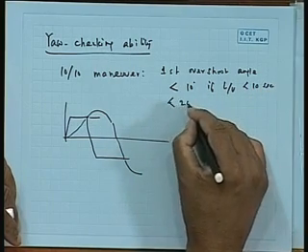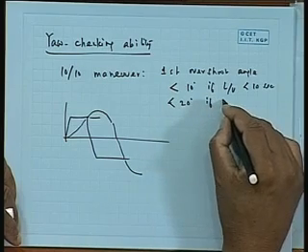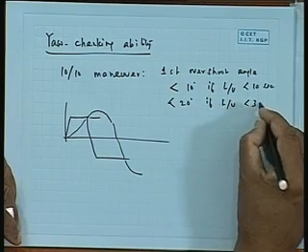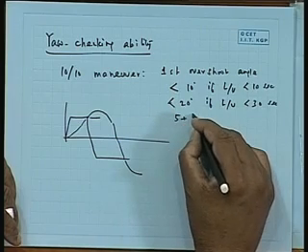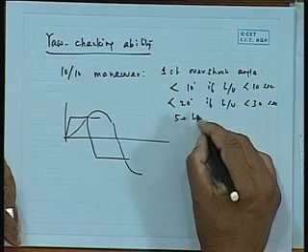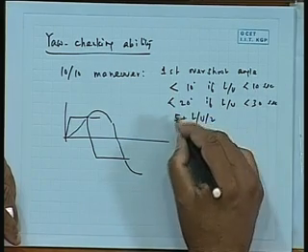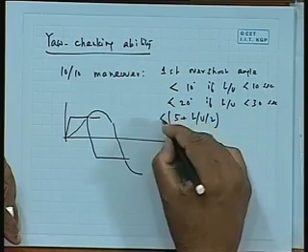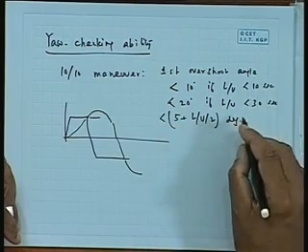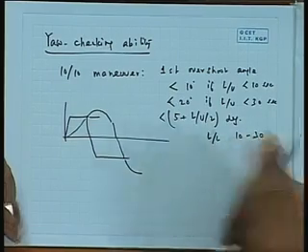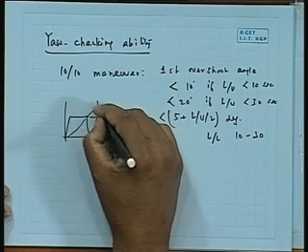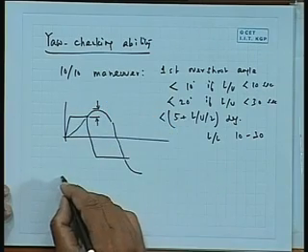Less than 20 degrees if L by V is greater than 30 seconds, and basically 5 plus L by V by 2 degrees for L by V between 10 to 30. Forget this part. See what it says here. Now this is a stipulation about the first overshoot angle, and also it says the second overshoot angle.